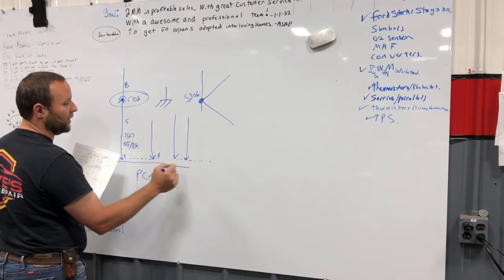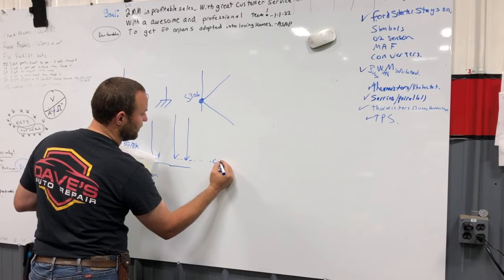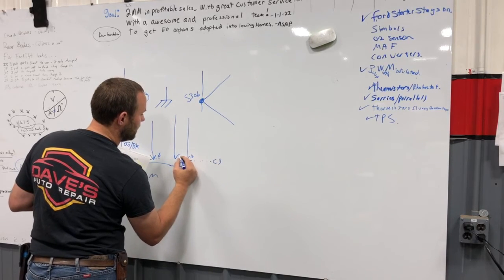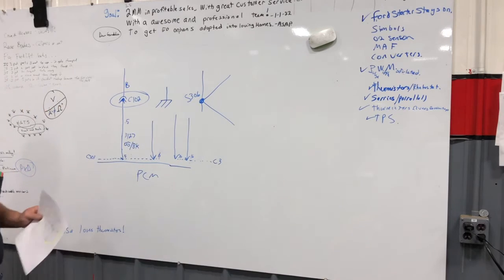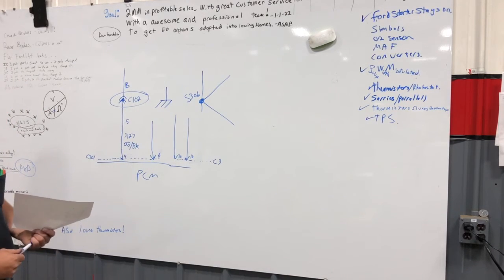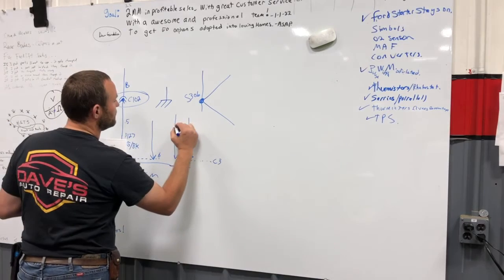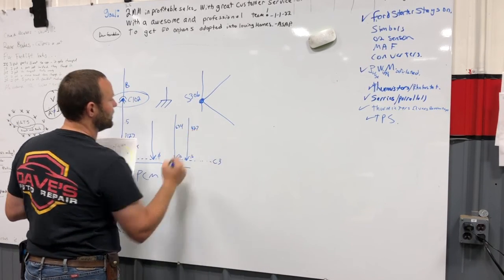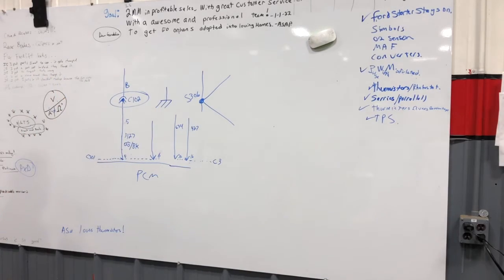If this line stops right here, there's 16 and 36. What's that mean? Is there another connector? You tell me. It's the new pin number in connector 3. Connector 3, new pin numbers? Yeah. Okay. What do those mean? Circuit numbers.